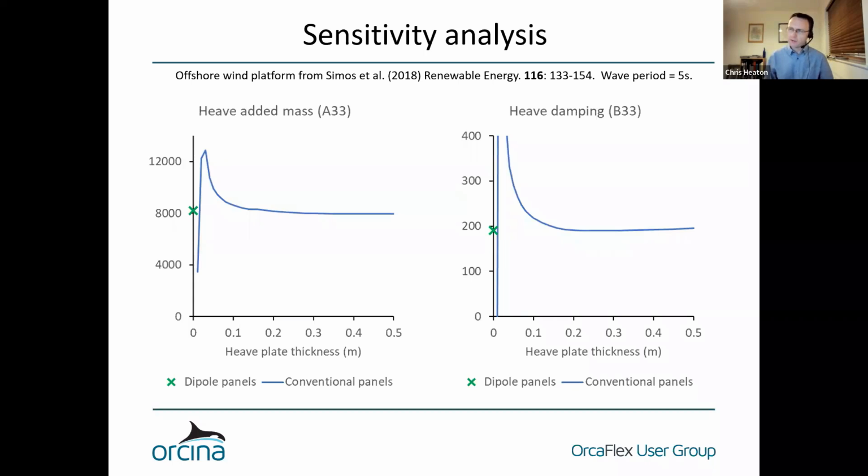I think the results look perfectly good out on the right hand side of these charts, but for thickness that's less than 10 or maybe 15 centimeters, these results are becoming unreliable, and that's definitely true of the real world thickness, which is 0.01 meters. That's somewhere down here in the numerical noise.